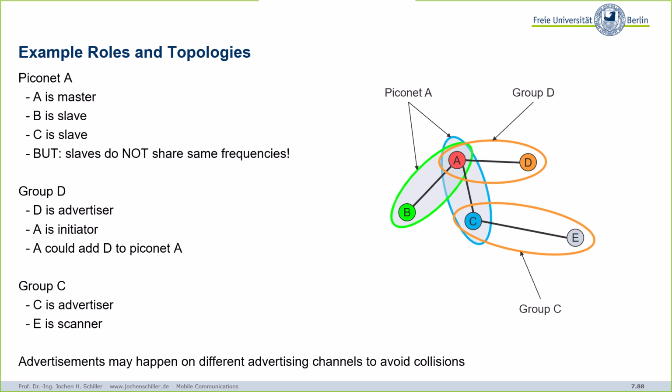And if you check, this is really going too far, if you check in the standard, you will see that from the higher layers on, the protocols Bluetooth Low Energy and classic Bluetooth use are the same. So in the protocol stack, they have more in common. It's just on the physical layer and part of the link layer that they are different. So different mechanisms, but you will also find these connectionless and connection-oriented services and all these things.